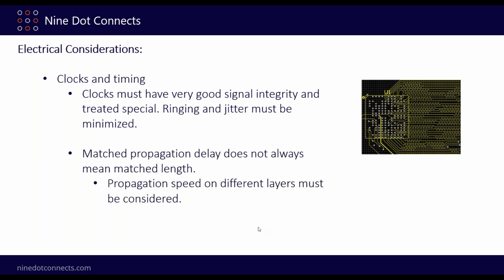Matched propagation delay does not always mean matched length. These days, timing is so important for some of these devices that we can't only use length matching. A lot of the EDA tools will allow us to check to see if traces are the same length.